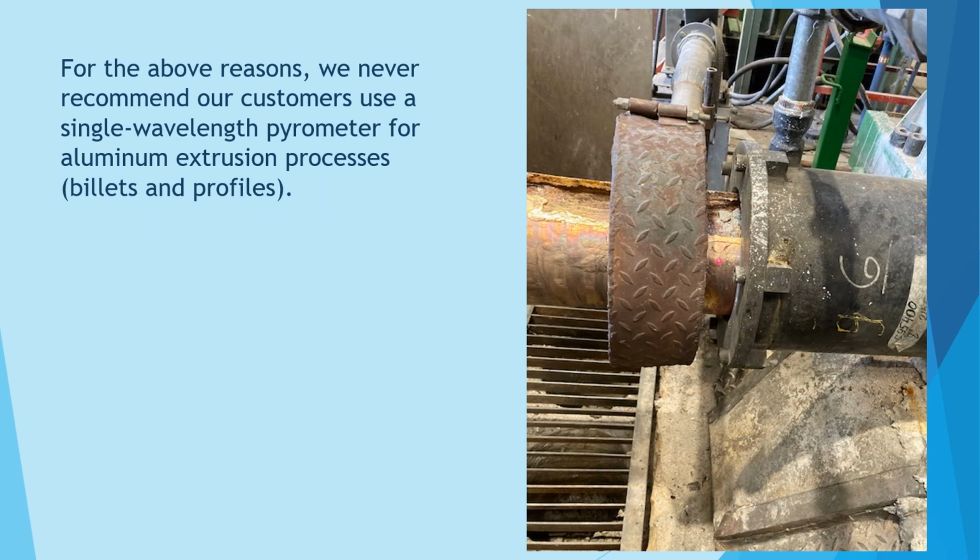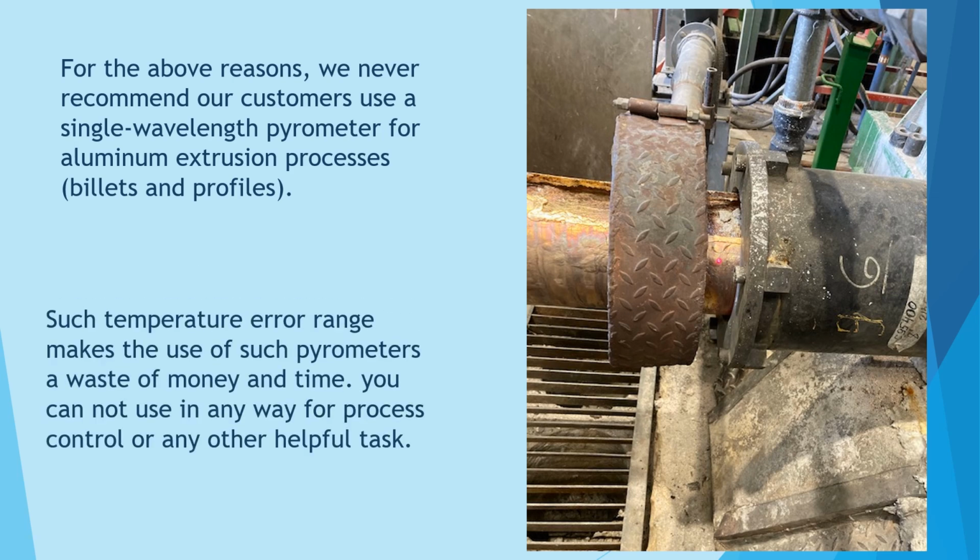For the above reasons, we never recommend our customers use a single wavelength pyrometer for aluminum extrusion processes, billets, and profiles. Such a temperature error range makes the use of such pyrometers a waste of money and time. You cannot use them in any way for process control or any other helpful task.